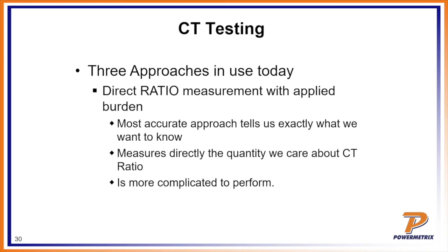What you're doing is measuring the primary, usually with a different type of probe, like a flexible current probe or maybe a high voltage probe like the Centraline probe. You're mounting it to the primary of the CT and then using a different probe at the meter itself. Usually we use a duckbill, which is a black and white probe you insert into the test switch to get the secondary current measurement.